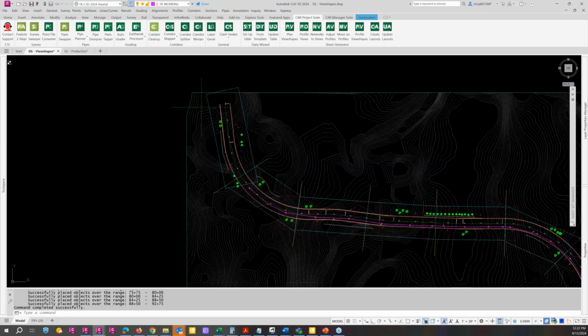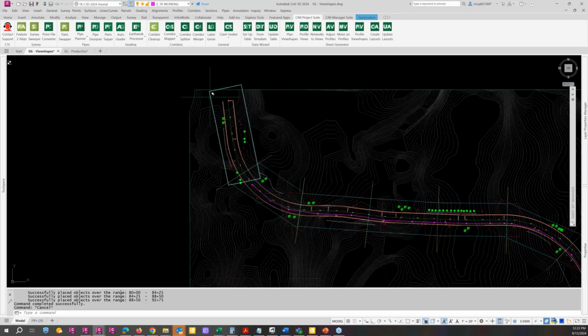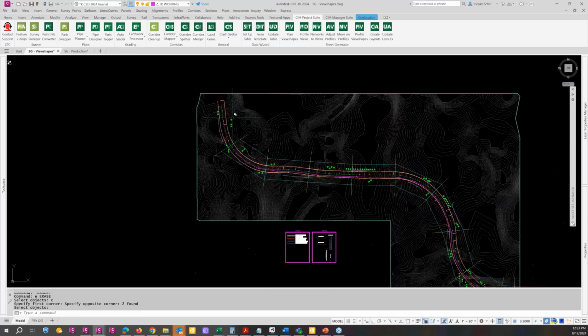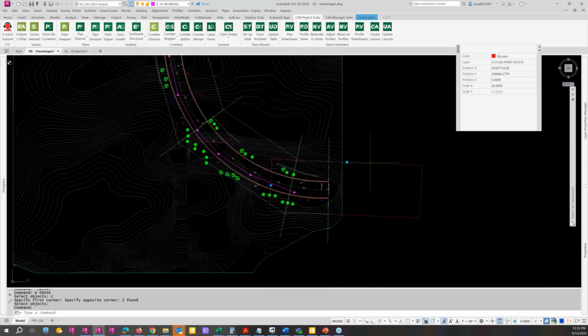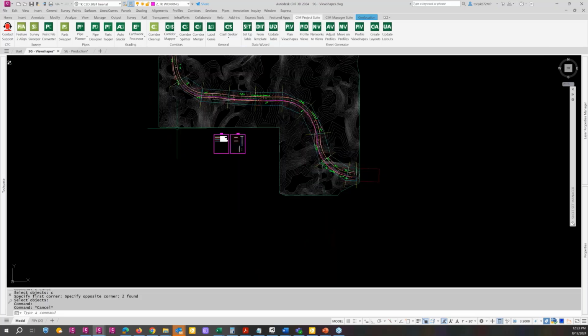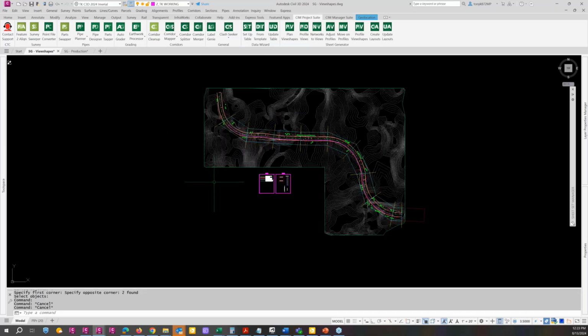And it hung on to this one out here because it didn't fall in there. So we can simply delete that out. It has no effect on anything else. So we have this last block layer right here, and you could make adjustments as you go along as well. Once we've got that and we save that, we can XREF it in.